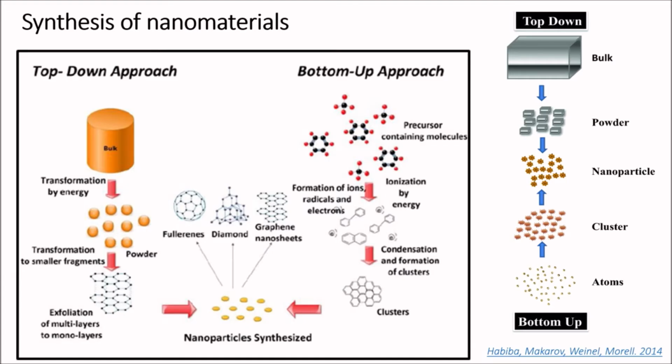There are two general approaches to the synthesis of nanomaterials and the fabrication of nanostructures: top-down and bottom-up approaches. The top-down approach involves the breaking down of the bulk material into nano-sized structures or particles. Top-down approaches are inherently simpler and depend either on the removal or division of bulk material or on miniaturization of bulk fabrication processes to produce the desired structure with appropriate properties.